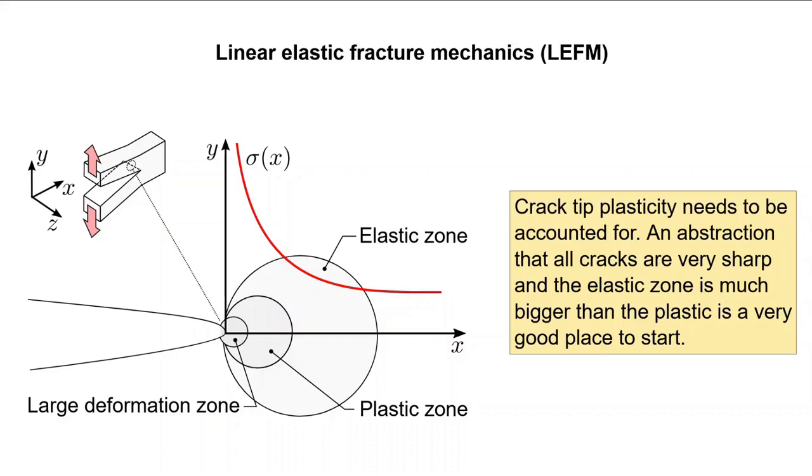This approach assumes that the elastic zone that surrounds a crack is much larger than the plastic zone. Therefore, we'll need to set some bounds on when and where you can use linear elastic fracture mechanics and the material properties that are used within this framework.